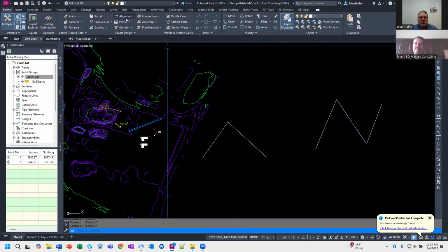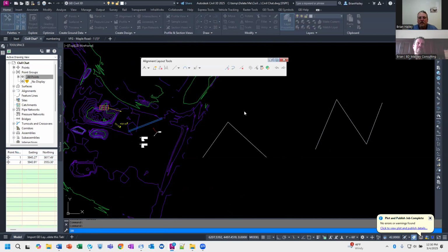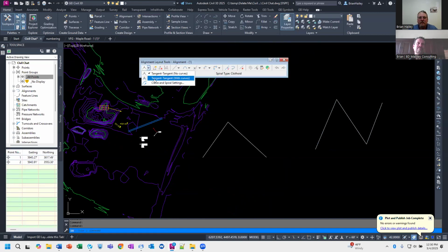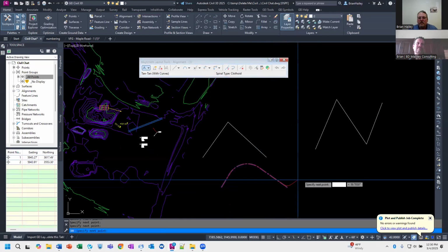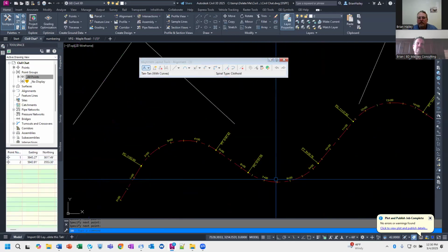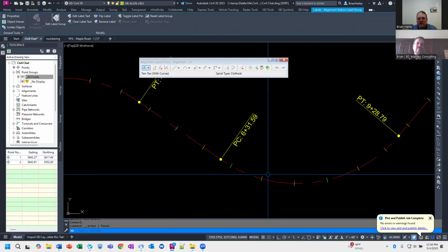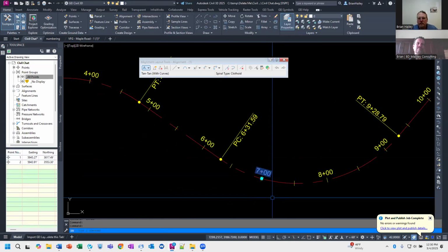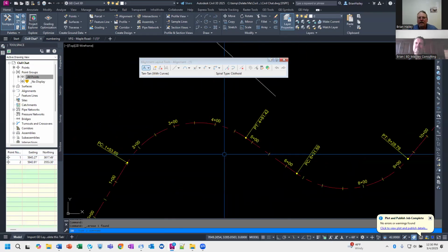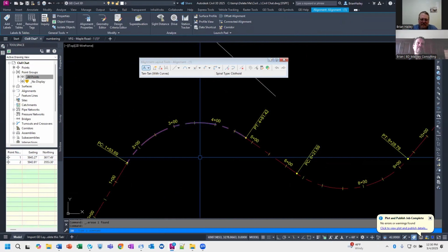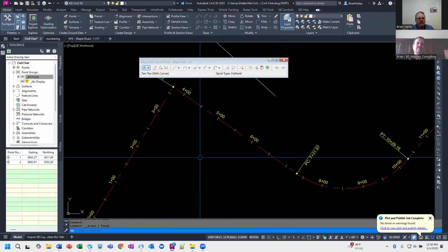All right. This also works on Civil 3D stuff as well. So if I come in here and I create an alignment with some nice curves on it, and I realize, hey, I don't want this label. If I select the label and delete, it deletes them all. But if I hold down the control key, I can delete just that one label. I can also hold down the control key, select the curve, and delete the curve off the alignment. So the control key toggles on your sub entity selection. It's fantastic. I love it. And it should be your left mouse button.